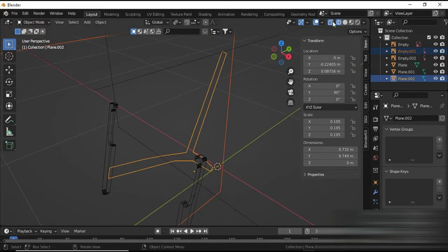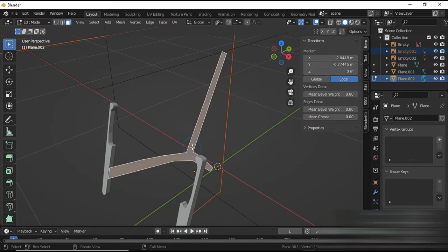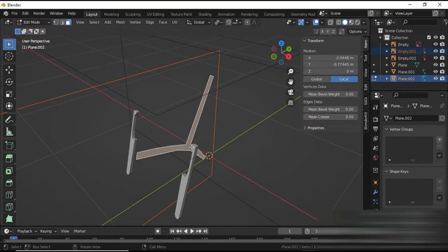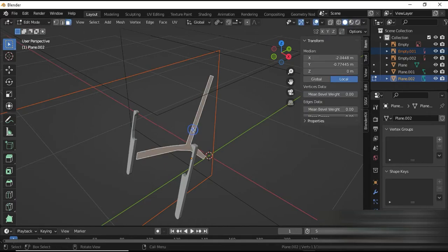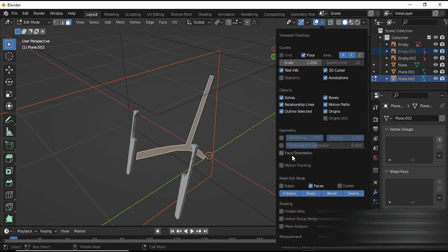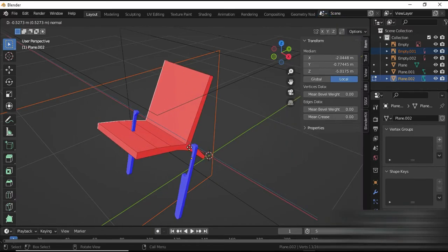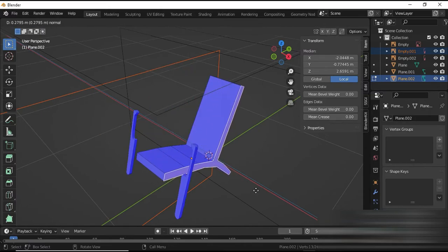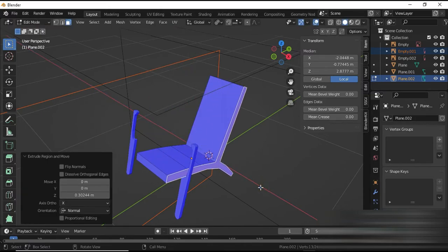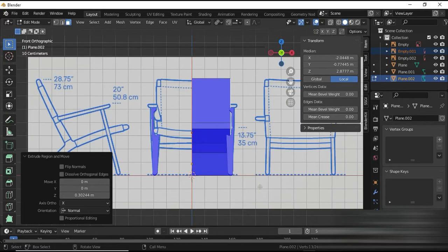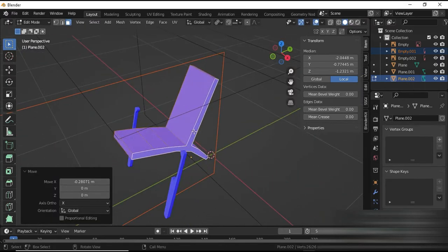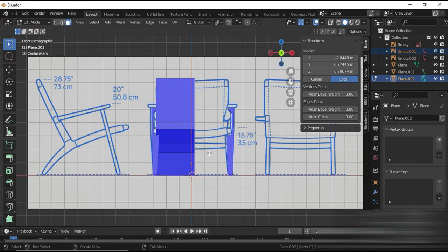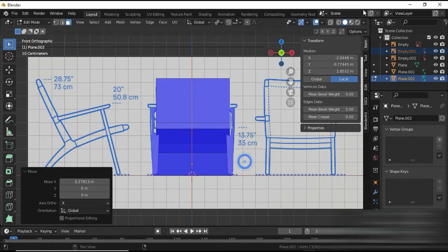Now let's get out from our resolution mode and let's press 3, and as I said before, do not extrude on the opposite end. You can't extrude on this side, it has to be on this side, otherwise we are going to be facing some problems. Now let's go to 1, so select all and G and X, that is done. Now select this face, back to 1, and G and X.